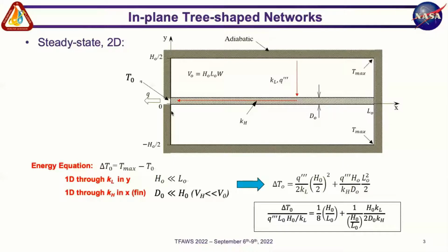So now imagine, we start talking a little bit more about thermal processes here. So this could be a cold plate generating a certain amount of heat, and you have a material of certain thermal conductivity. So the question of how are you going to distribute your high thermal conductivity material in this volume to optimize the reduction of this maximum temperature is related to the structures that we've seen before. In tackling this problem, you of course have an infinite number of alternatives on how to distribute this material in this volume to reduce your Tmax.